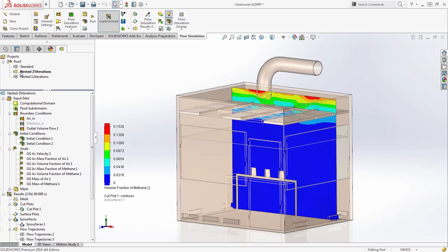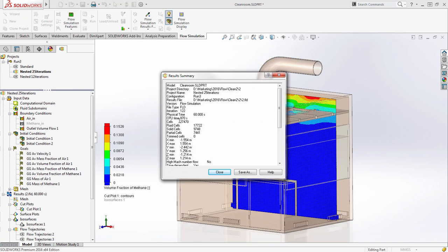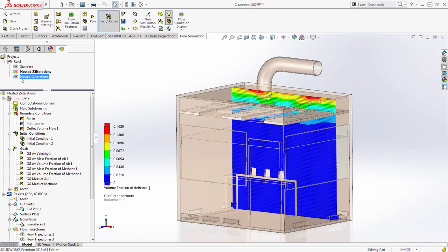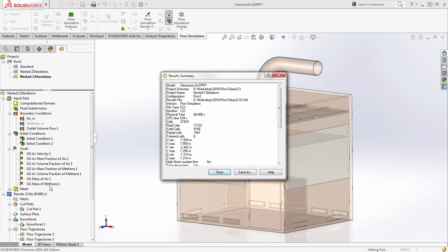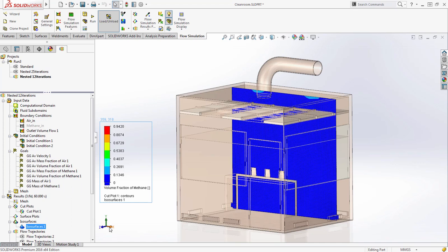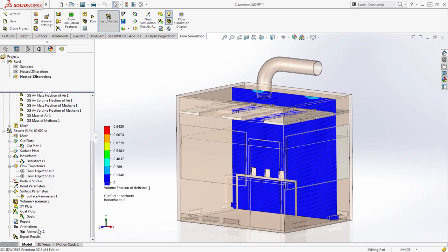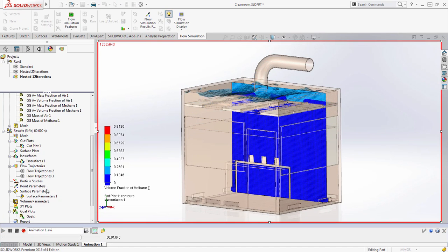With the nested iteration control set to a maximum of 25, that comes down to 970 seconds, or a 26% time reduction. With the nested iteration maximum set to 12, this further reduces to 534 seconds, or a 59% reduction. So a substantial saving for the solution time, which is very beneficial for making sure we can quickly evaluate results and ensure the product performance meets our requirements. So some great benefits for time varying analysis in 2016.